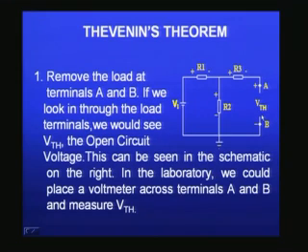So if you want to measure, it is very simple. Open circuit, that is, remove the RL from the circuit and use a multimeter, measure the voltage across the output terminals A and B under open condition. That gives you the V Thevenin.